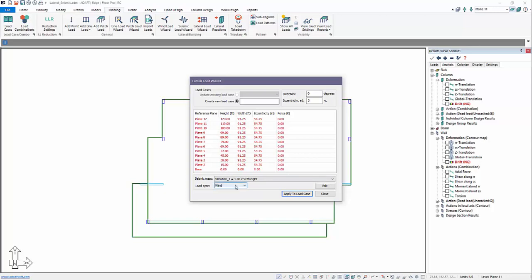We define whether it's a wind load or a seismic load. Here, we distribute the forces, again, nodally, both the forces and the moments, but the user would input the combination, the story forces, eccentricity, and direction. And the program treats these types of loads identical to how we handle the seismic loads produced from the wizard.